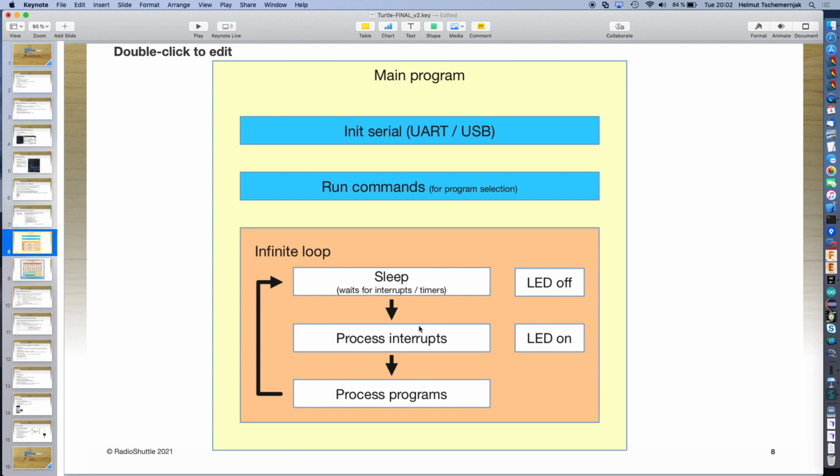And once something is happening, like a timer or a user press or some other event, it takes a few microseconds, and then it processes this and may go to sleep again, or it puts out some data, and after this is finished, it goes into deep sleep. So this loop is very, very important, because you don't want to do synchronous waiting or processing. Everything needs to be done asynchronously with timers and with callback functions, just to make sure that you sleep all day long to save energy for this board.